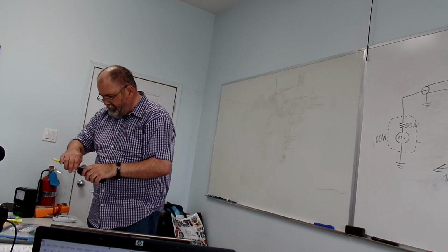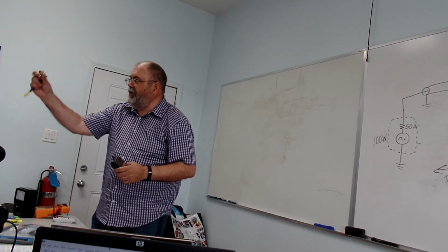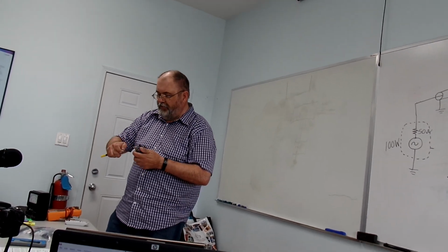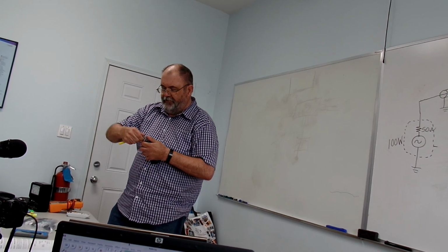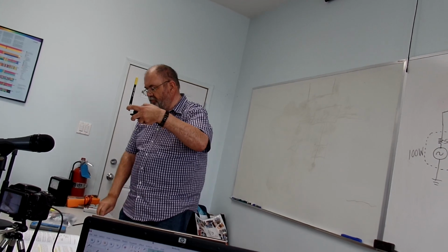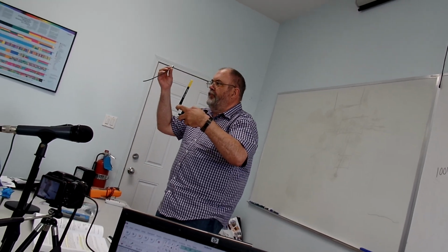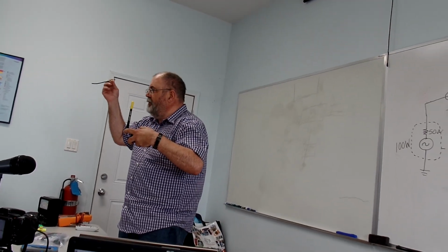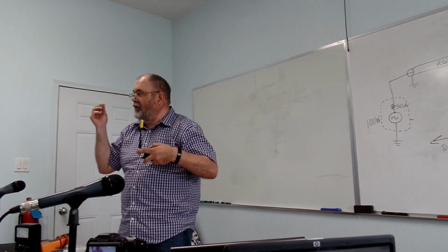You hear what I'm listening to? So I'm going to take the antenna off. This is just a BNC T connector. So I'm going to put a T connector on, and I'm going to put the antenna back on. And hopefully... This happens to be a quarter wave of RG58 at 162.4 megahertz. I measured it this morning in my easy chair.